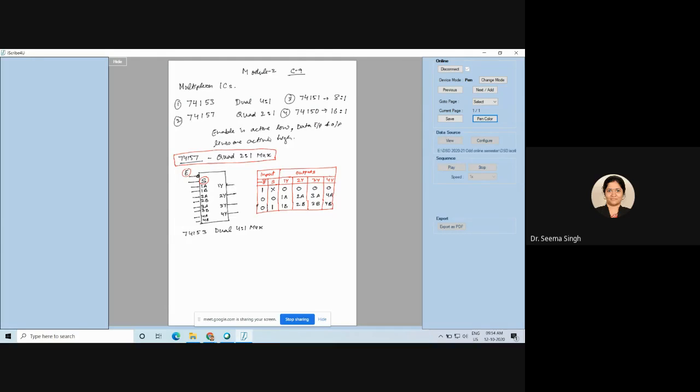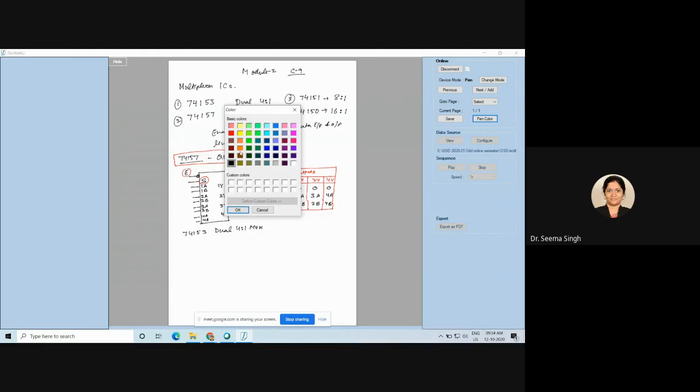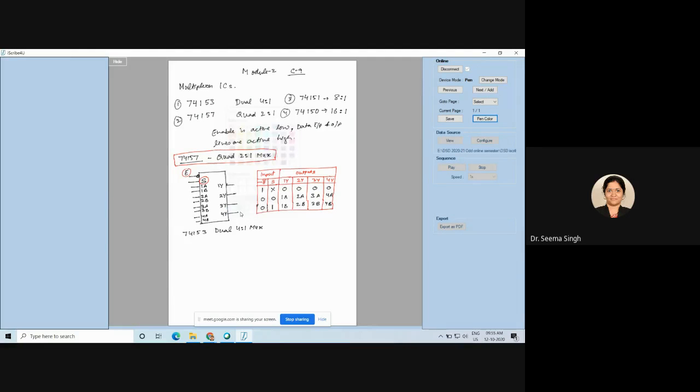Now I can show you the block diagram as well as the pin diagram of the IC. Now for example, for my previous mux also, I will give you the pin numbers. Let me show in a different color. Why? Because when you use it in lab, you should remember these numbers also. So select pin is pin number 1. Then 1A, 1B is 2, 3, and output should be near to this.